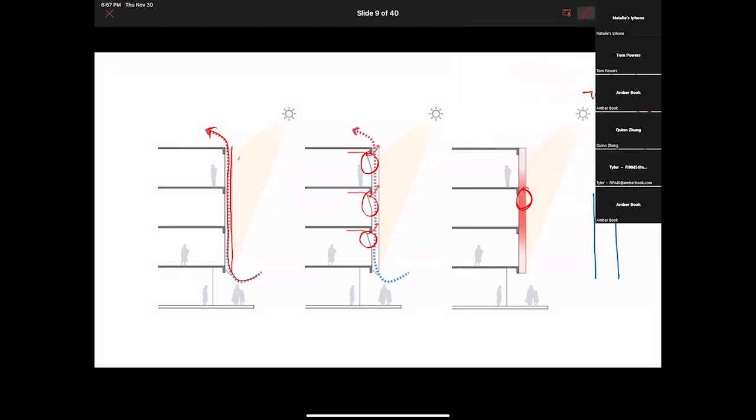But yes, in the summertime it brings this air up, and it brings cold air down on the inside. So the 90-degree air is being moved to the inside by basically a handoff or a handshake between the air within the cavity. If that cavity is greater than 4 inches, it's likely to happen. That's a rule of thumb. If it's a very tall cavity, it will happen even at lower widths. So you don't want to create a convective loop ever. Nope, never. Got it.